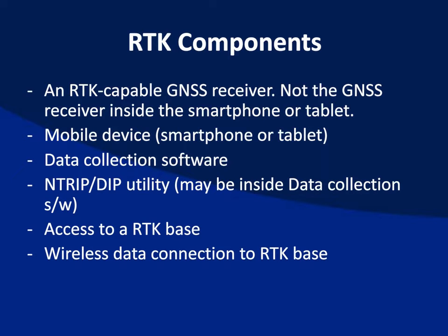And then lastly, we need a wireless data connection to the RTK base. Historically, or classically, it's been a dedicated communications link like UHF radios or 900 megahertz radios. But these days, with the proliferation of mobile phones and the expansion of mobile phone networks, more and more people are trying to use, and can use, their mobile phone networks as a wireless data connection to access RTK bases.